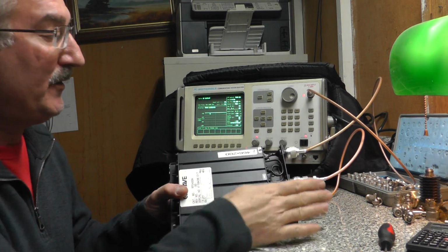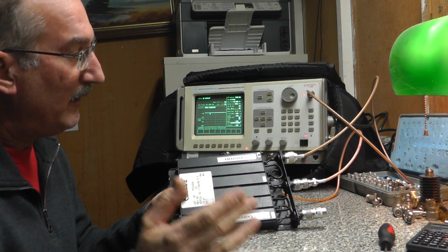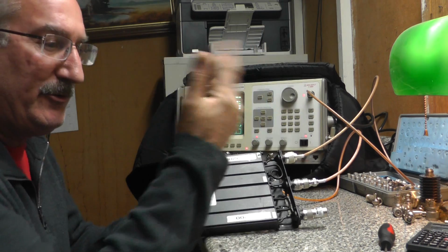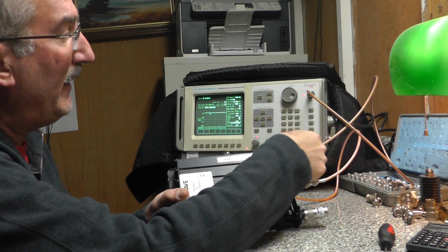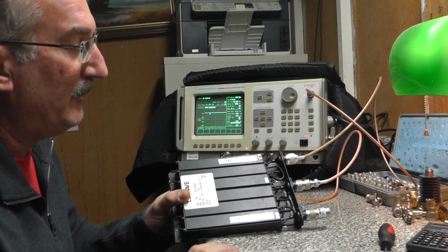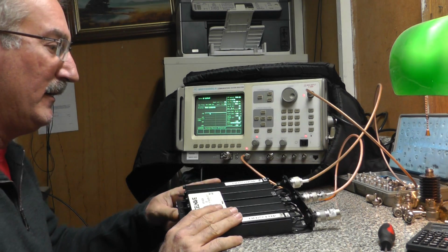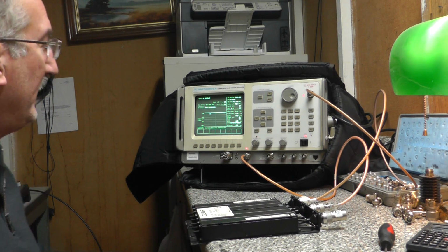So I've connected this up now with our source going into the antenna, because that's where the receive frequency is going to come into the device, right? And then we're going to have our detector, our antenna input here over at the receive port, and we put our dummy load on here, our 50 ohm impedance matching device there. And now let's take a look at what we have.